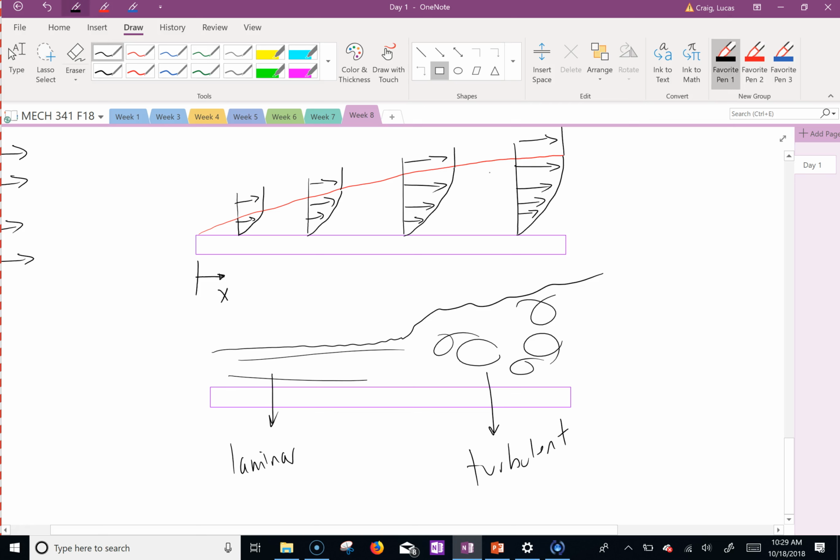The boundary layer is not very far. The other thing we had to worry about was location right and left, because if you have an inlet straight ahead of you, you don't want to be measuring in that. So you have to know the wake region of that. We had to try new spots, and we found one that actually worked right. Yeah, on the belly. We compared it to two or three that were in the front of the plane, way up top, because you can do it on the top too. And we compared our measurements, and they were comparable. But when we moved it, it wasn't even getting close because something upstream was interfering with our measurements.